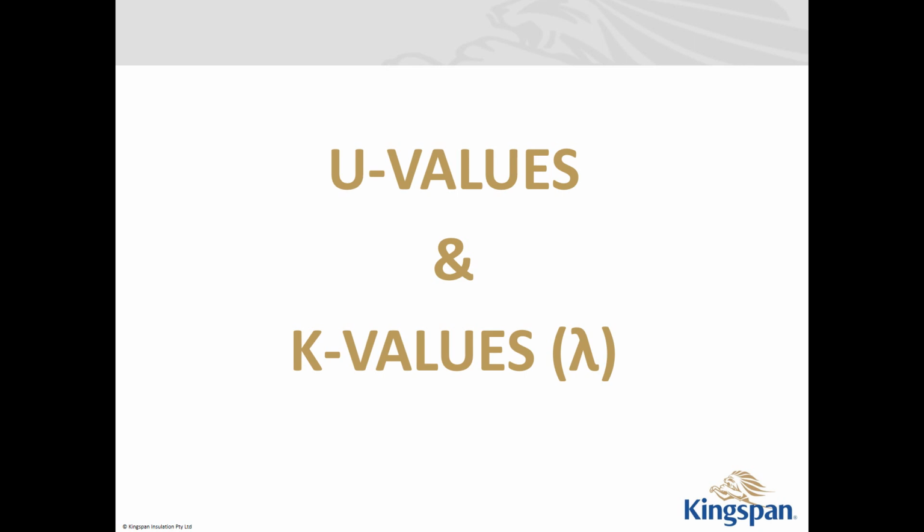So how do they go in the tropics though? Because do you really want insulation in the tropics? Well, that's different. The difference now is in the tropics, your typical Queenslander type houses, or your Northern Territory type construction, they've always built the houses with plenty of cross ventilation, so you can open up windows and doors or screens and have some air blowing through the house to try and keep them cool, or keep the house as close to the ambient temperature as possible.